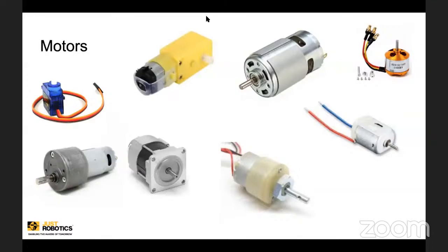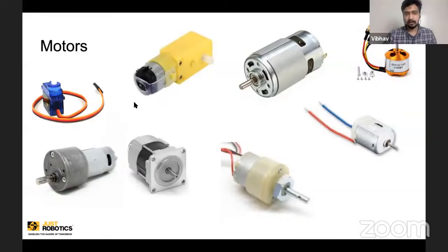Okay. So the BO motor that you buy in the market will not come with the wire terminals attached to it. You have to solder the wires into the motor, or you have to ask the vendor to do it for you. Okay. The same case with any motor. Sometimes you don't get the motors readily with the wire terminals. So that is something that you have to take care of.